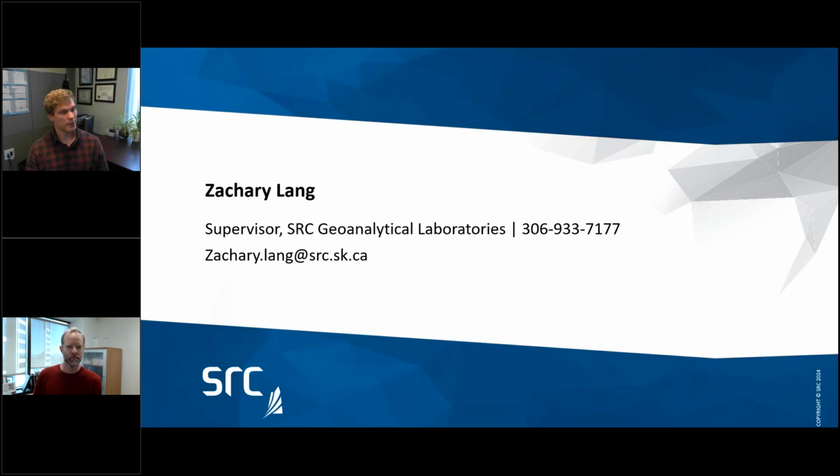As for DMS or density separation, cyclones themselves are a lot cheaper, but you also need all the infrastructure and the pumps to go along with it. So DMS is probably a little bit cheaper if you already have the infrastructure, but if you have to put the infrastructure in place, it kind of depends. How many sorters do you need? How many cyclones do you need? Because you can get a lot more bang for your buck. It's easier to get multiple cyclones in one installation than it is to get multiple sorters.